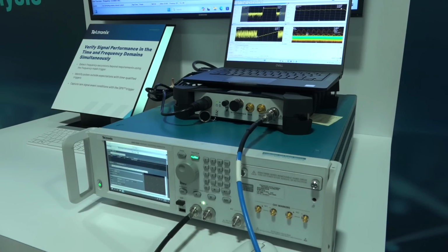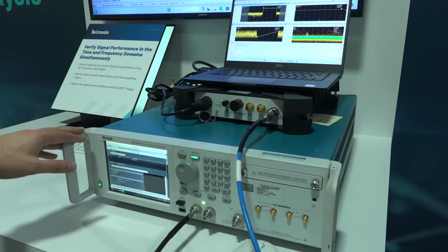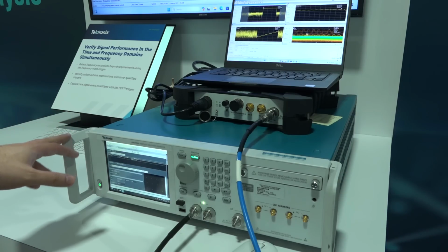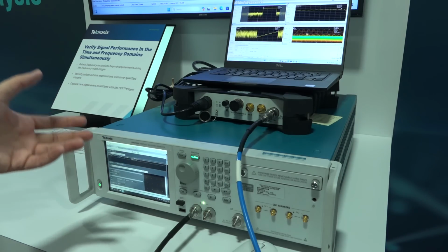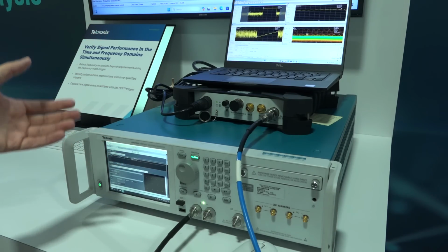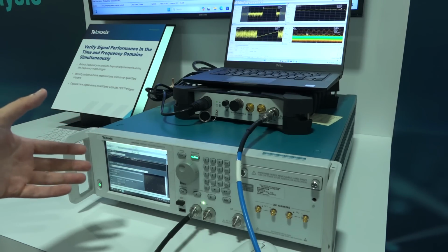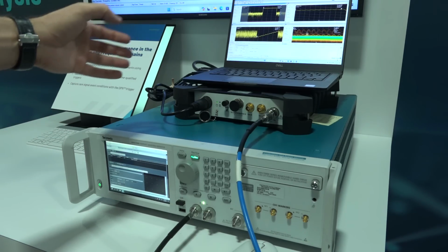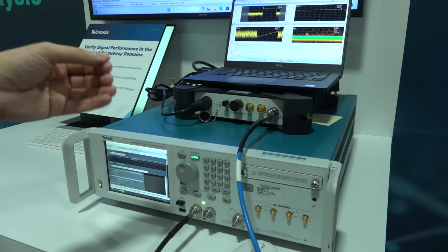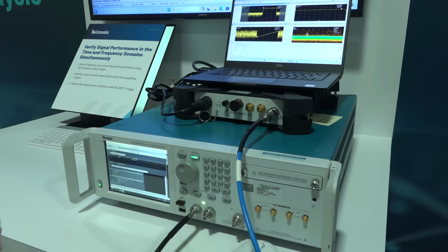So here on the Tektronix booth, they're combining the AWG7000 with one of their real-time spectrum analyzers at a carrier of 10 gigahertz. Often in very complex signal generation in the RF domain, it's difficult to separate various RF events from each other, because everything is mixed together. So you need advanced triggering and advanced signal processing techniques to extract a single piece of information. Here in this example, they have a step chirp going through, and there's some anomaly or event buried inside this complex waveform that's passing hundreds of times a second, and you need to figure it out and bring that out.